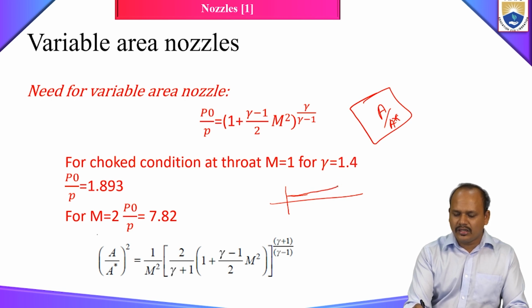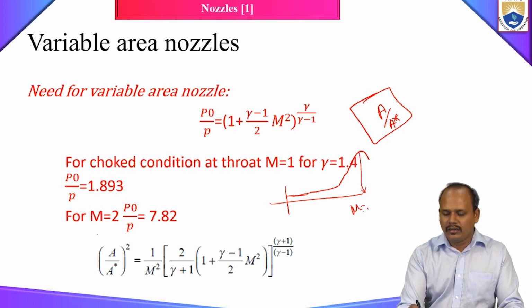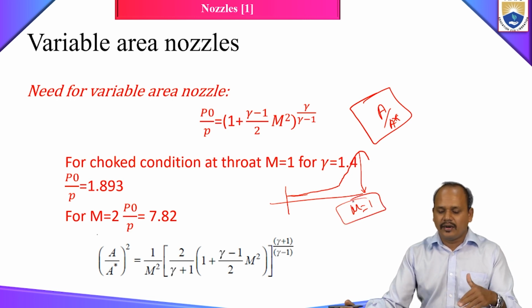When it reaches the sonic zone, that is transonic flight, your drag increases rapidly, almost 10 to 20 times. That is at M equal to 1, where your drag increases to a very high value.